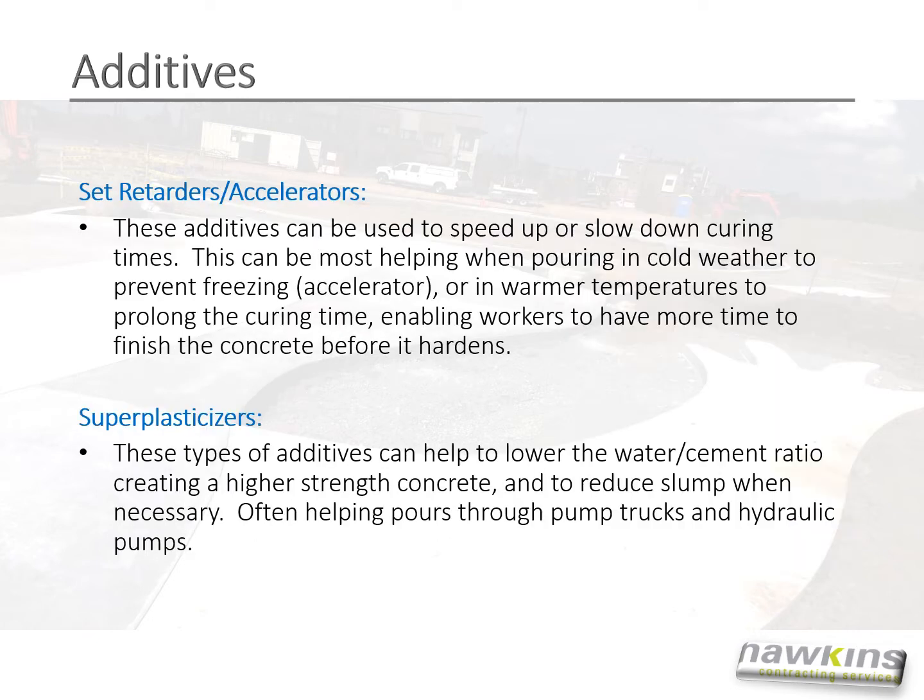Set retarders and accelerators. These additives can be used to speed up or slow down curing times. This can be most helpful when pouring in cold weather to prevent freezing, or in warmer temperatures to prolong the curing time, enabling workers to have more time to finish the concrete before it hardens.